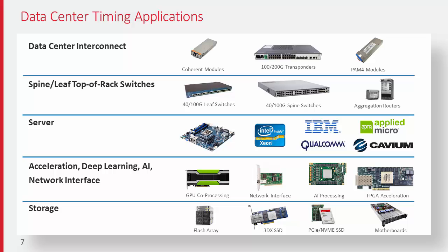What exactly is driving these requirements? Is it mostly tighter jitter requirements, or can you expand on that? You're right, definitely tighter jitter requirements. From Gen 1 to Gen 3, the data rate for PCIe has increased from 2.5 gigabits per second to 16 gigabits per second. So higher data rates require a more accurate clock.